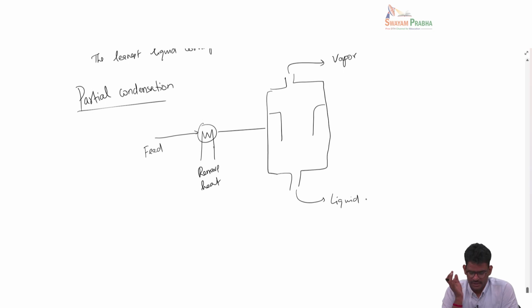So in terms of the design equation, you have exactly the same equation, because it is the same operation, same flow sheet. It's only whether we add heat or remove heat. If I do an enthalpy balance for this problem, that will be slightly different. As far as the mass balance is concerned, it's the same thing. So, you can use the same set of equations I derived before for both flash distillation as well as for partial condensation involving a single stage operation.